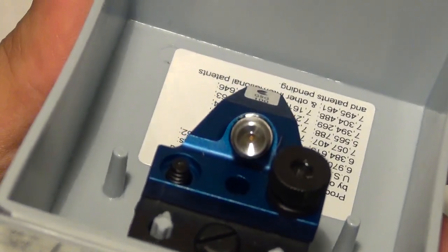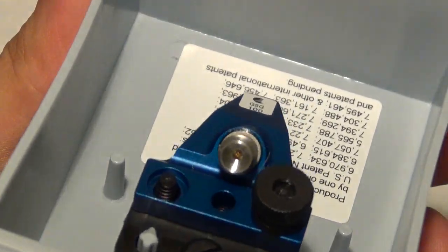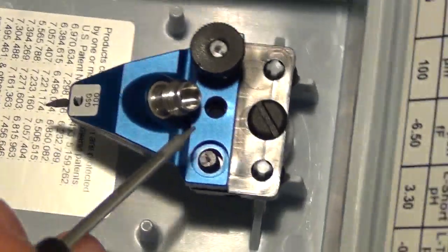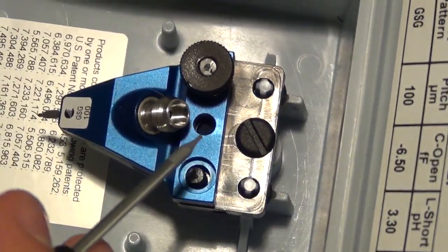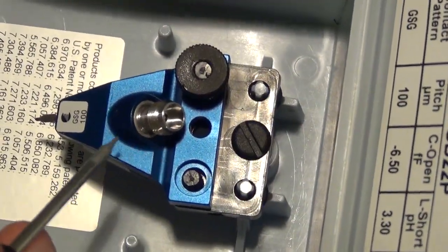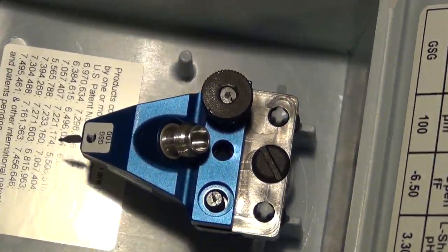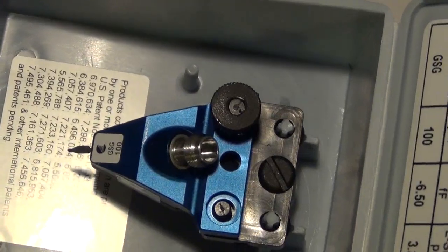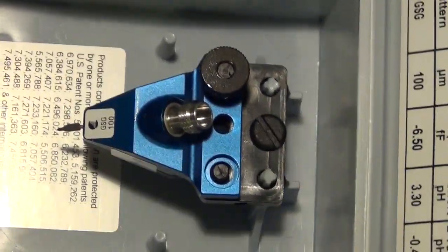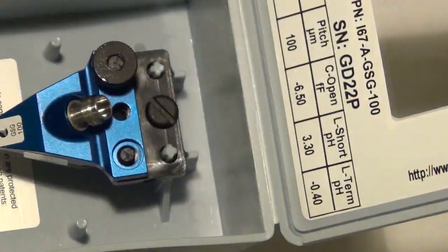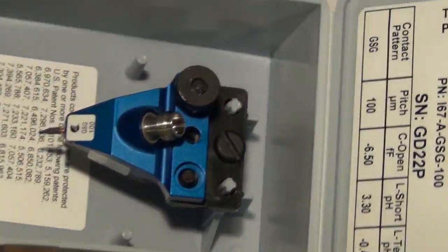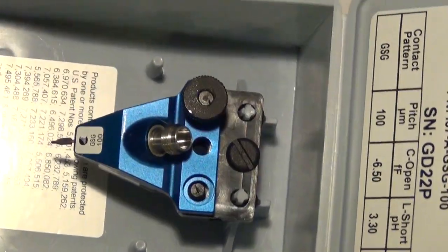There it is. This is a brand new probe. Very expensive, and you have to be extremely careful with this. Always use a proper torque wrench when you connect with this. Make sure you don't allow the connector to turn. Don't over tighten them, because these things will just break off, and then you can't really repair these, even though you can, but the repair cost is almost as much as a new one. So you might as well be very careful and make sure these things don't break. They do have a limited life cycle. You have to be very gentle with them.